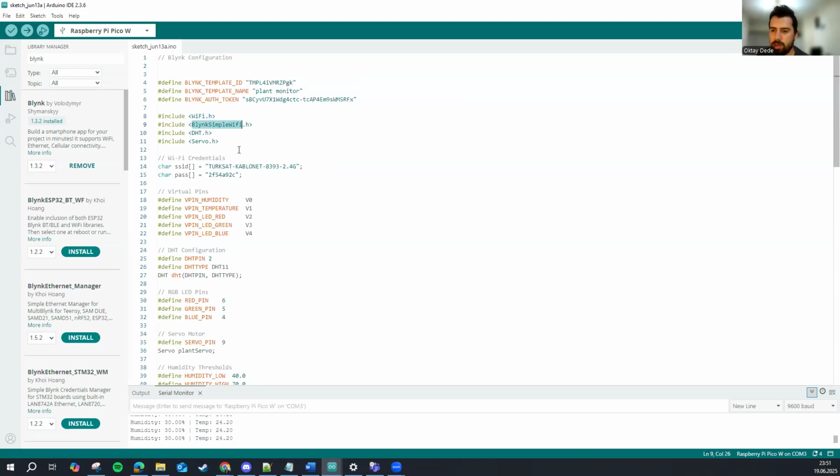I used DHT11 module, which can monitor humidity and temperature levels by setting up a circuit. And I used a servo motor, which controls the watering system that is later going to water the plants automatically or controlled by your remote application or remote device. Then you need to add your Wi-Fi credentials to the board, which the board needs to connect to Wi-Fi to enable communication to a web server.